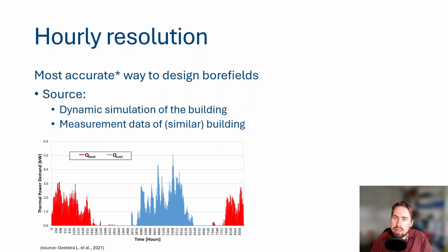Because if you obtain this data with high accuracy for a building that's only more or less your particular building, it can be that your geothermal simulation is not that accurate after all. But assuming that your hourly profile is really representative for your building, your HVAC system and the climate, then we can say that this resolution can give you also the most accurate bore field temperatures. And here below we see again a load profile for such an hourly simulation, where you have hourly loads for both heating and cooling.